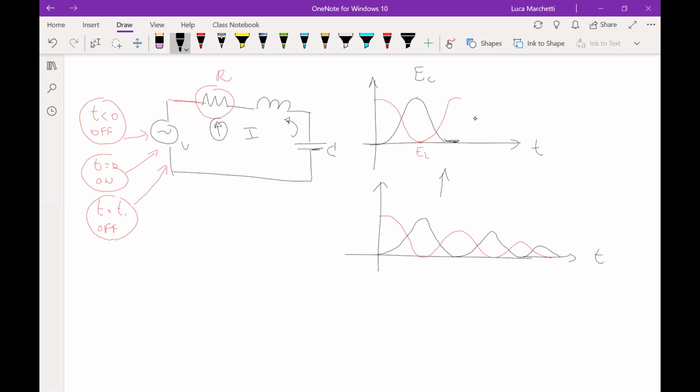If the resonance circuit works correctly, then this capacitance and inductor will exchange energy indefinitely, infinitely. So if this resistance was zero, in theory this circuit would oscillate even without the power supply, even without the input signal, and continue to oscillate indefinitely. However, unfortunately, because the wire has a parasitic resistance, we already talked about it, any circuit has parasitic resistance. So little by little, the energy exchanged by L and C is going to reduce. But I wanted to talk about this just to talk about the quality factor, as I was starting.